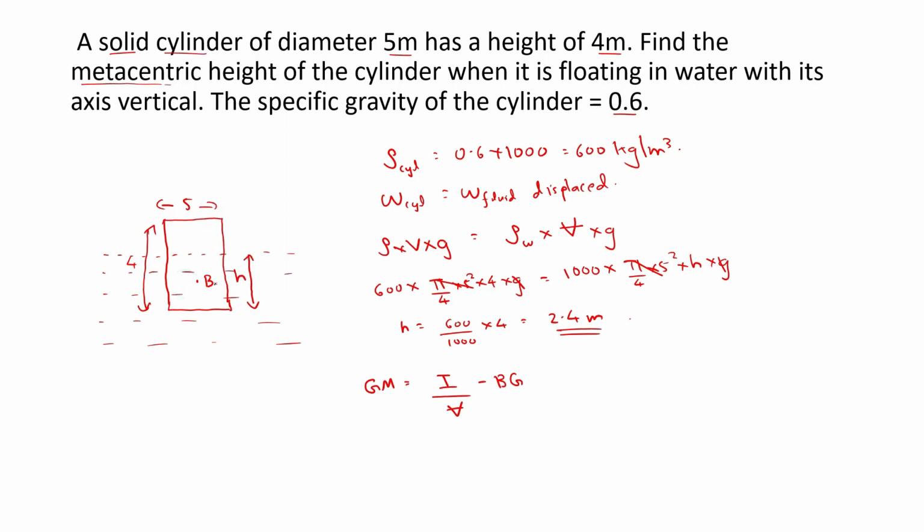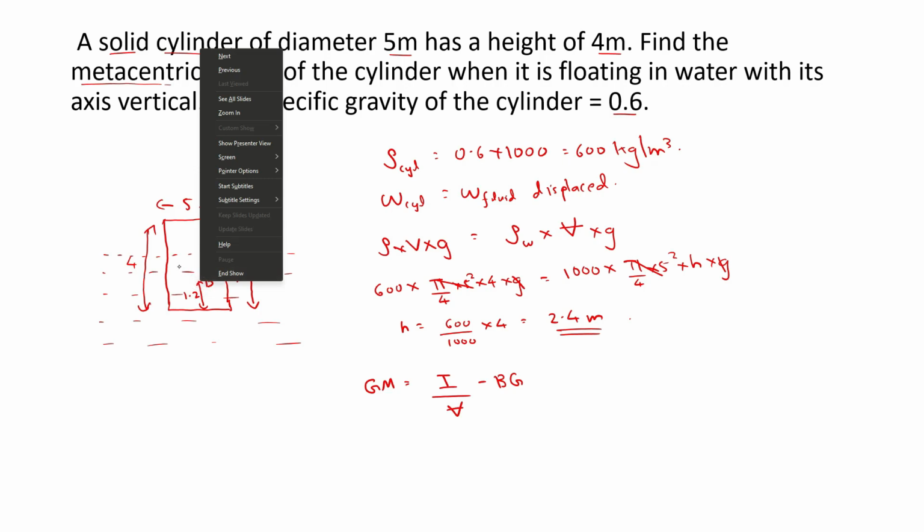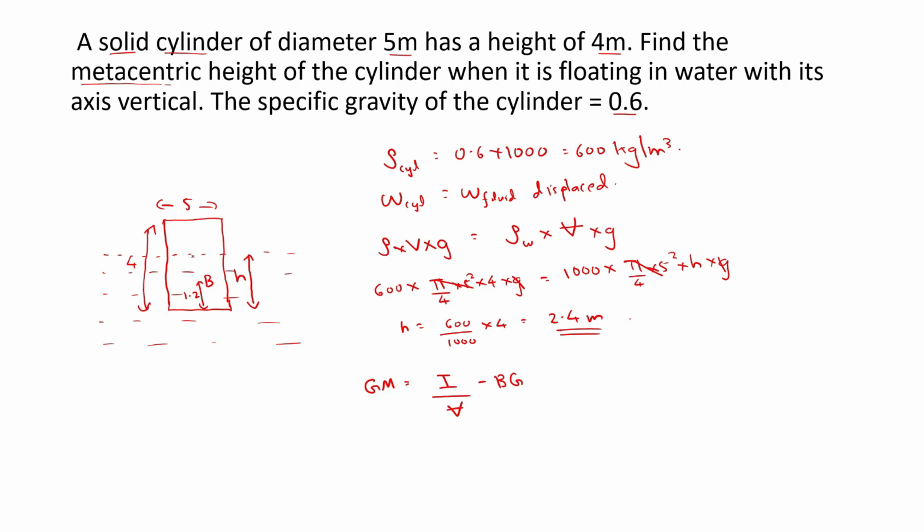The total height is 2.4 meter, so this will be 1.2 meter, the center of buoyancy, and the center of gravity will be here, at a position of 2 meter, since the total length is 4.